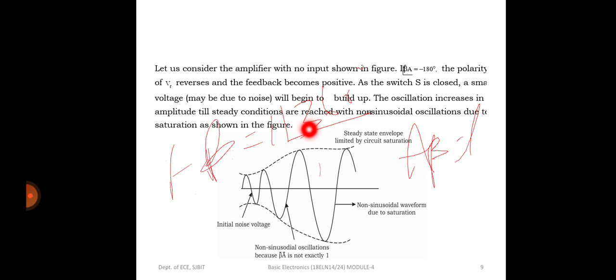Thus practical oscillators can be produced when an amplifier consisting of an active device is combined with a frequency selective feedback network to determine the frequency of oscillations. So if a device is going to act as an oscillator, then it is mandatory to satisfy the Barkhausen criteria.